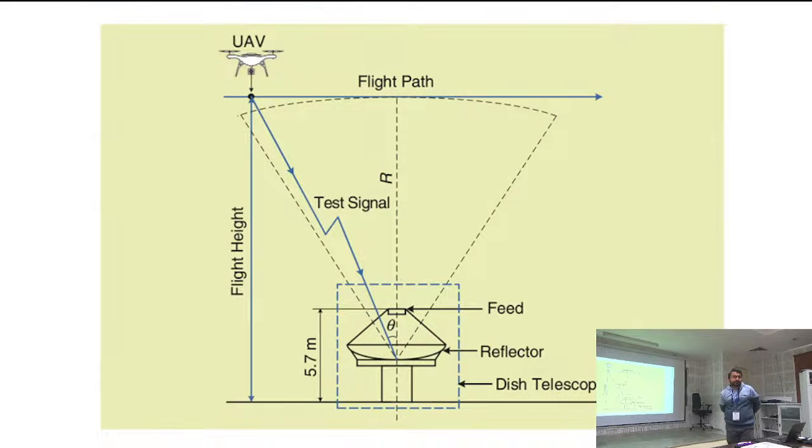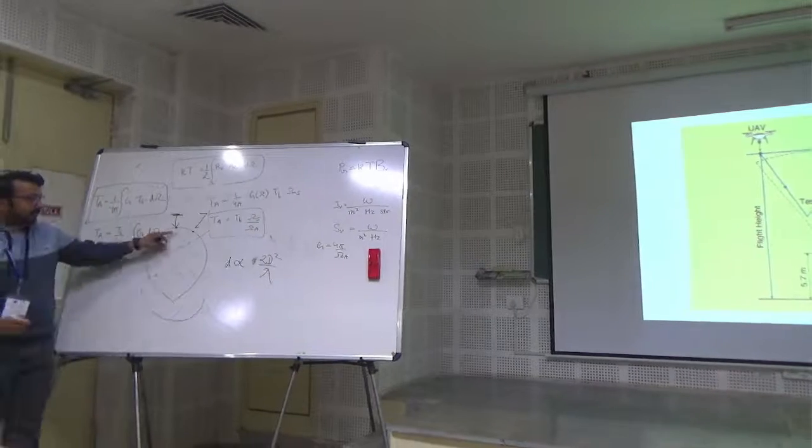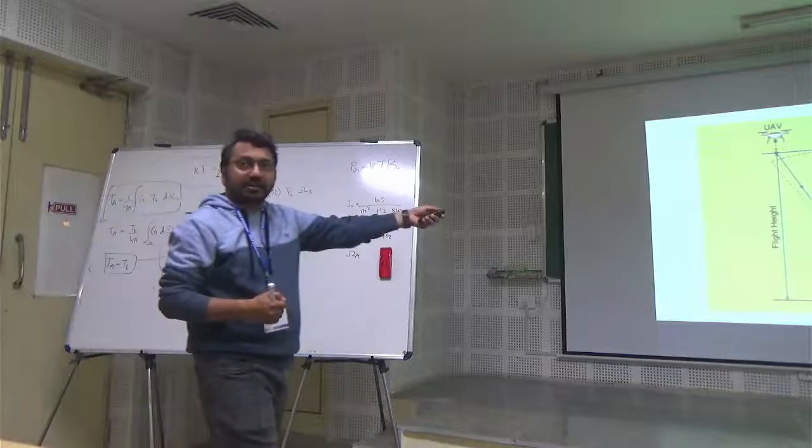The antenna is always directing towards the same angle. Suppose my dish is this, my radiation pattern. The drone here is transmitting right here. Now when it goes here, if it transmits like this, you will find the gain attenuated by this ratio to this ratio. So this projection effect you have to take into account, even independent of the trajectory.